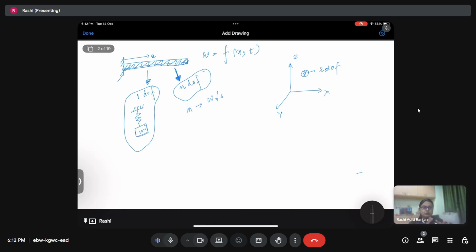However, it all looks good when we talk about single degree of freedom, n degree of freedom, or even continuous systems when our system is linear. When we get into a nonlinear system, even a 1 degree of freedom system that is nonlinear, we can't even get the closed form solution, right? So when we are talking about a nonlinear system, things become more complex, and then the choice of how we should model our system becomes different. However, here we will learn how to solve questions related to the continuous system, because definitely if a system is working in the linear range, then we can use the basic concepts of partial differential equations in order to find the solution. Okay,